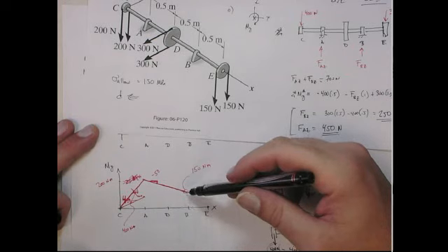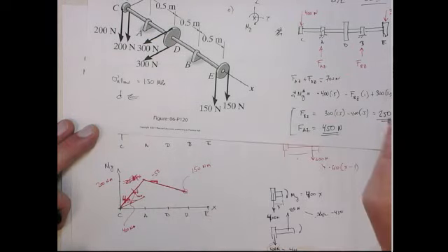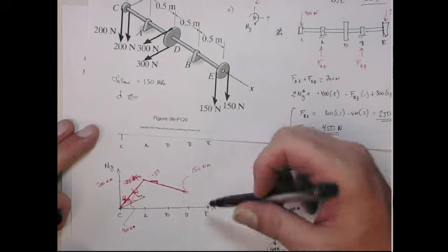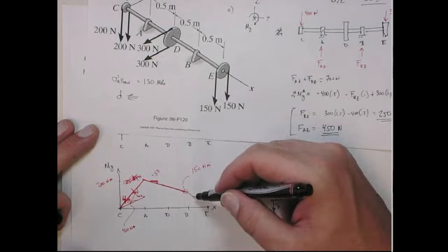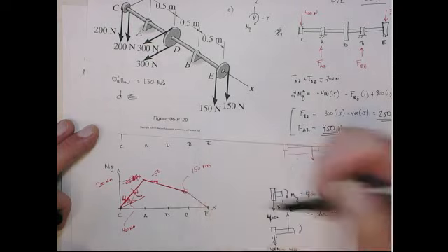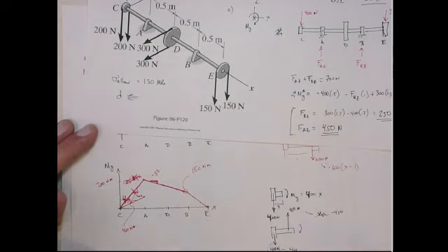The slope was at minus 50, so when we drop off another 250 off the slope, it becomes minus 300 over half. It goes down to 0 here, right? So every time you add a point force, the slope of the curve will change by the value of that point force, right?